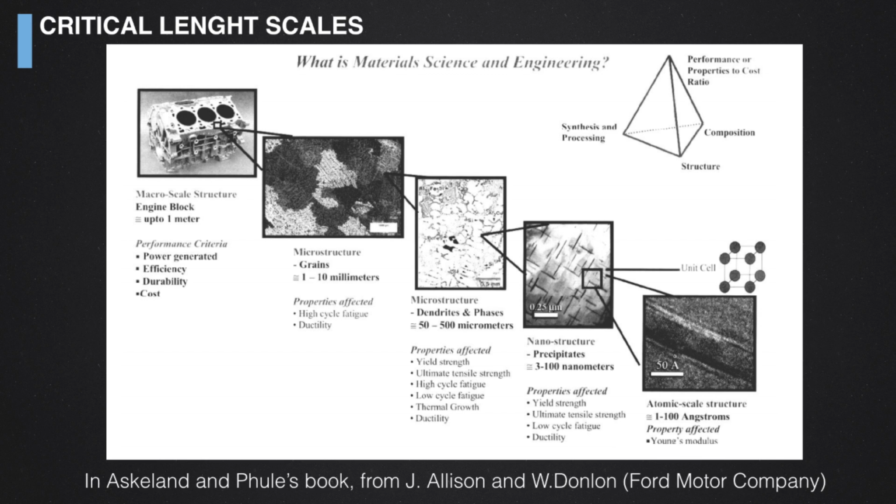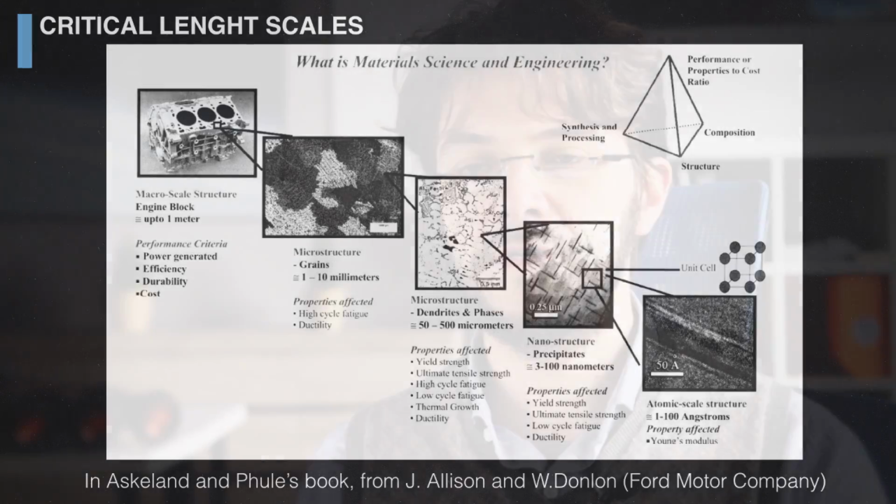Those precipitates may be even graphite flakes or intermetallic compounds, in particular cementite, which is the Fe3C compound. So it's a perfect alloy that has the exact composition Fe3C, and it has a huge mechanical hardness, but also it's very brittle.